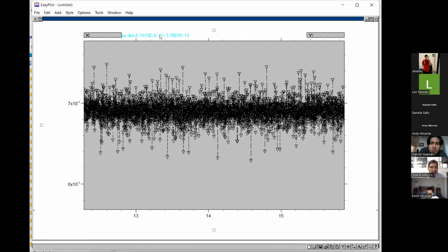And you see here, this is the value. The mean value in this case is 6.9 e to the minus 5. So remember, this is strains, okay? You multiply by 10 to the 6, and that will give you microstrain. So that would represent 69. That means that this is the strain that you measure at this point when you apply the maximum load.